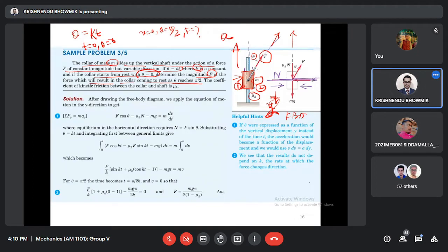Say something happened due to the friction, some wear happens. Say this is the mechanism people are using, and you are the designer. I'm showing the cross section. If wear happens, it is supposed to happen here, wear and tear, because this will be the contact zone. So the design will be such that this side should be strong for this case.